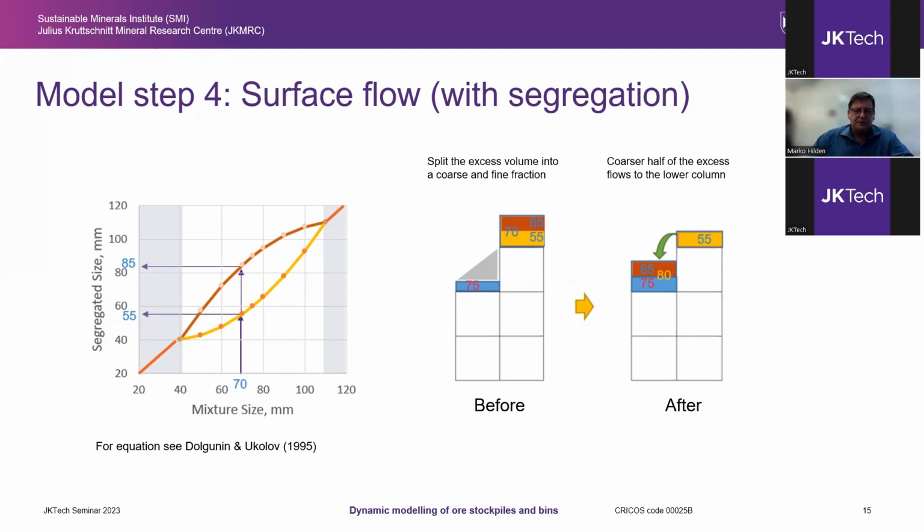The first parameter is the fine size. When a region in the pile only contains fine particles, segregation rate slows down. Likewise, when a region in the pile only contains coarse particles, coarser than the coarse size parameter, the particles can't percolate between each other, so segregation rate reduces. The final parameter essentially describes the breadth of this lens shape.